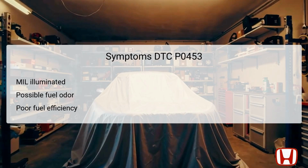Drivers may observe several symptoms related to DTC P0453. The most notable is the illumination of the malfunction indicator lamp, MIL, which serves as an alert for potential issues within the emission control system. Additionally, drivers might notice a fuel odor, which can indicate a leak in the EVAP system, potentially due to a faulty FTP sensor or related components. Furthermore, high voltage detected by the FTP sensor can lead to erratic behavior in the fuel system, resulting in poor fuel efficiency. This combination of symptoms underscores the importance of diagnosing and addressing the high voltage condition promptly to avoid worsening problems and to ensure that the vehicle meets emission standards.